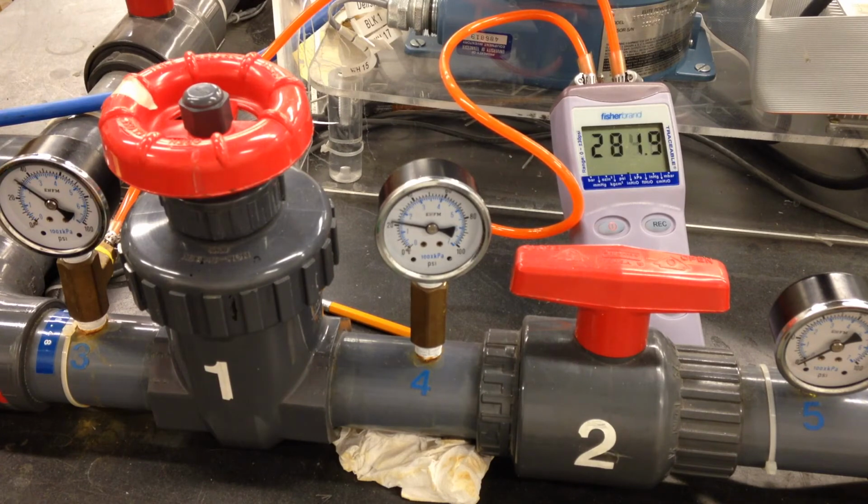I know in class many times students will try to spend a lot of time getting the so-called exact flow that's being called for, and that's nice in some applications. Here, however, what we're really interested in is not the exact flow we call for, but to know what the flow is and what kind of effect it's having, what kind of result it's getting out of the gate valve. So with that, we will proceed to our procedure. We will start with the quarter and we will go outward to the full opening.